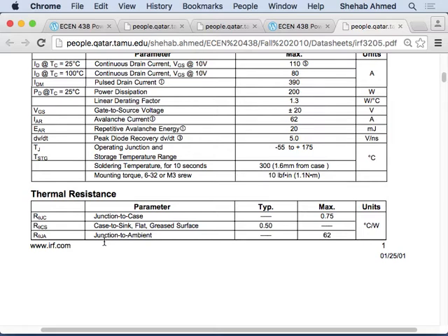It's not. I said that we are going to put some triangles so that we make our life easy to calculate. We ignore whether you include or not the time delay, the turn-on delay versus the rise time, the turn-off delay versus the fall time. Fine, it's okay. It's an approximate number anyway. Just take their average value, or take a number, or take them both. As long as you show me what you're doing, I'm happy, right? And you'll get a ballpark figure. But this ballpark figure is plus minus 25%, for example, right?